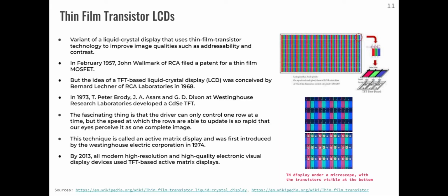So these tiny transistors control the level of brightness of each subpixel by using a tiny voltage to represent a single color as per the instructions of the graphics driver of our computer. The transistor will vary the brightness of green, red, and blue subpixels separately. And when we combine millions of these subpixels together, we get our image.